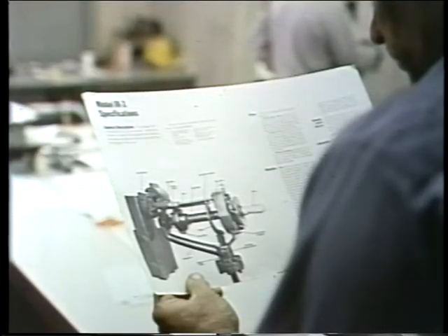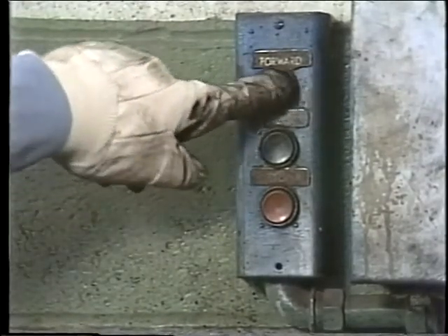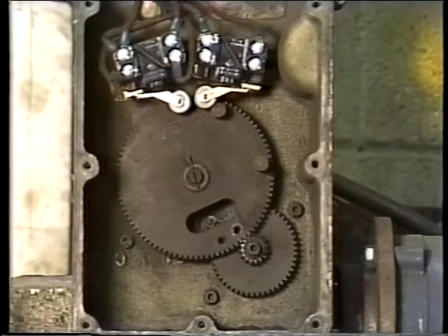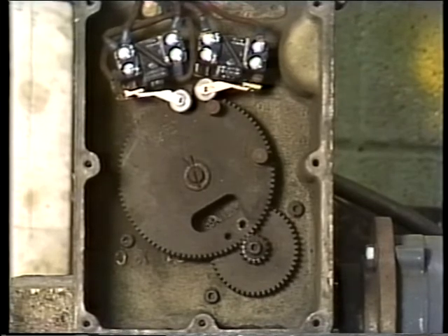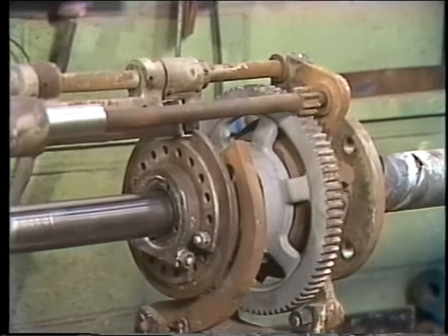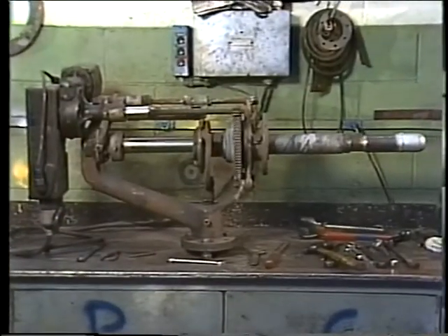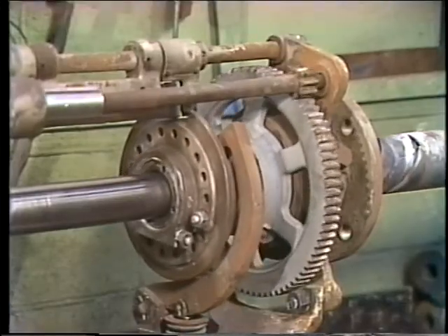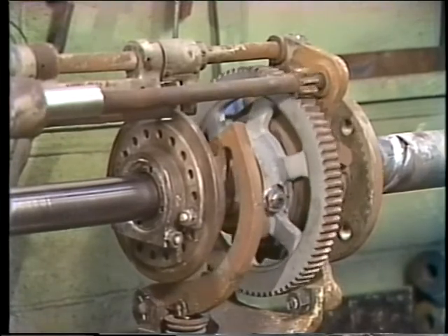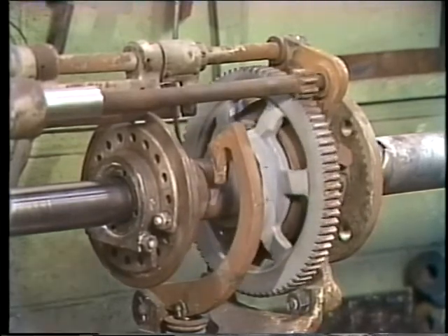Before he performs the bench test, the worker looks up the proper cycle for this soot blower. This way, he knows what the device is supposed to do. A simple start-stop reverse switch controls the drive. The drive's limit switches stop and reverse the drive automatically. The automatic cycle extends the element, rotates the element 2 full turns, and stops and rotates the element the other way 1 full turn before driving the element back to rest. After bench testing the soot blower under power, it's ready to go back into service.